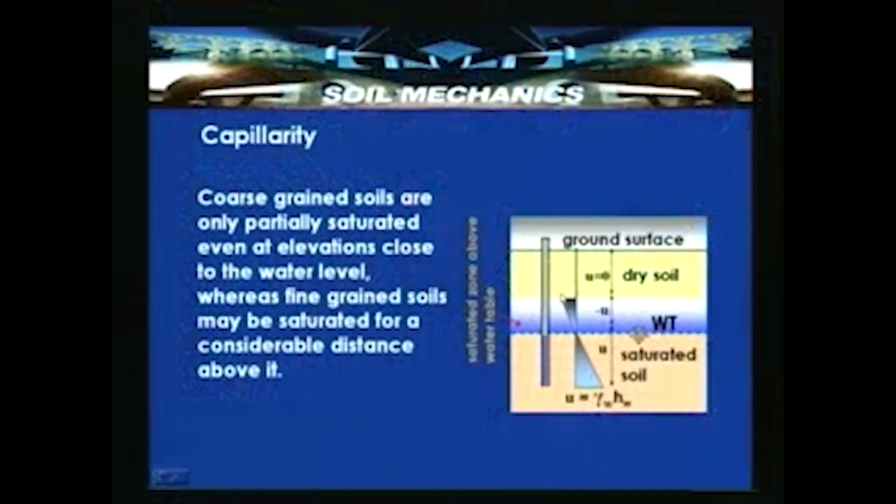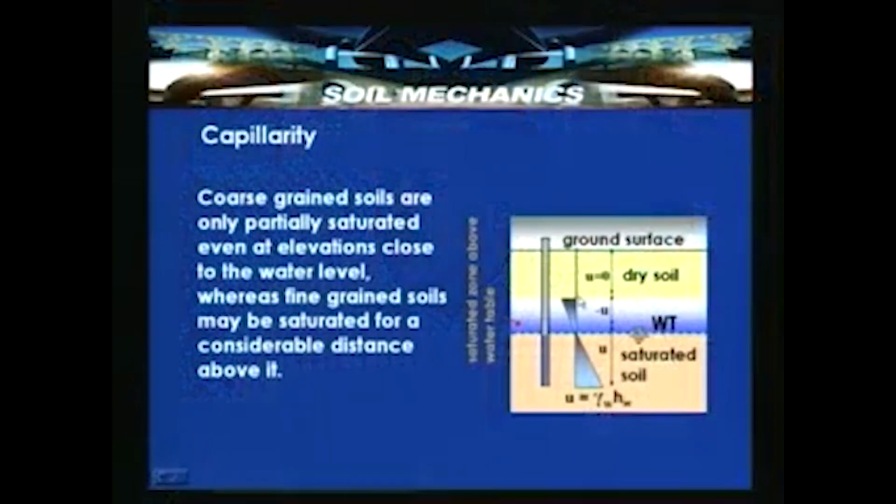So, above this the distribution of the pore water pressure can be, if there is a partially saturated soil, then it can have a certain reduced pressure. But otherwise, if it is immediately say a dry soil coming where the capillary rise is almost negligible, in that case it can run like this, a negative pressure. That means this ordinate is nothing but HC, the negative head which is kept above the water table, that is minus gamma W HC, which is nothing but the negative pore water pressure. That will be there, and then immediately the pressure can be dropped to something like zero pressure.